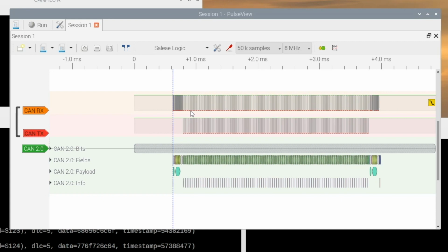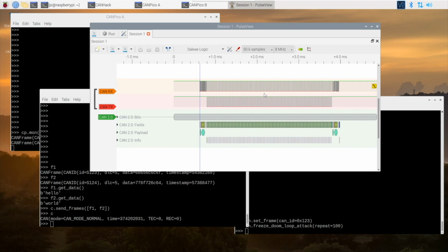For example, we could force a timeout to happen because when we see a certain frame and another frame is expected in the application, we can force that second frame to be so delayed that it triggers a timeout and some kind of recovery process. Or we could combine it with other attacks to generate spoofs at particular times, and then delay the time that the sender tries to send its own valid frame to be passed any time the software would look at it. So this is extremely useful if you're an attacker, to freeze the bus at arbitrary points and trip up all kinds of application functionality.